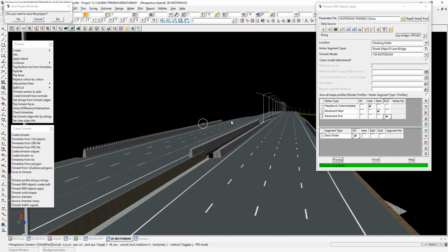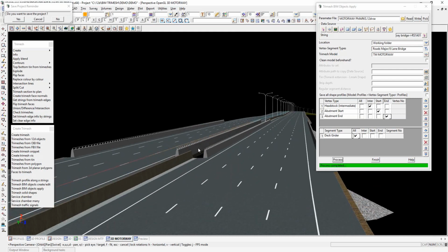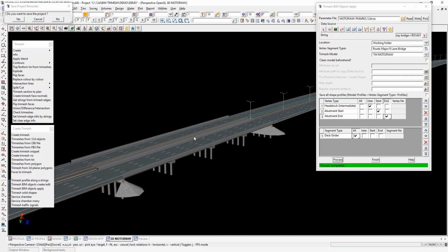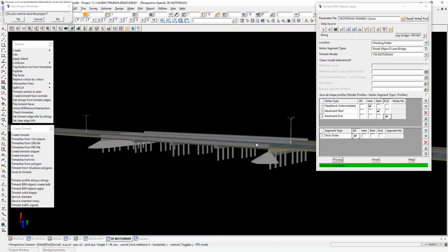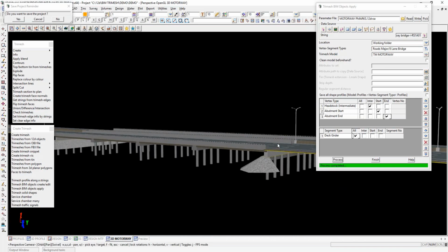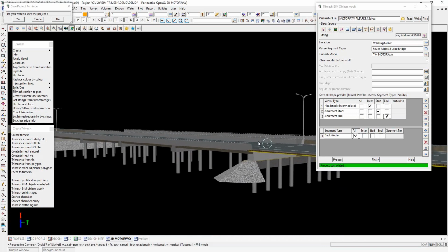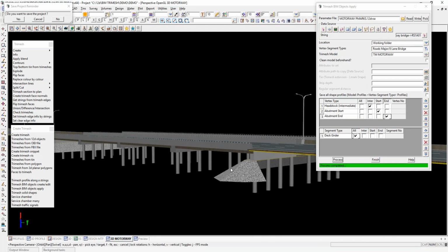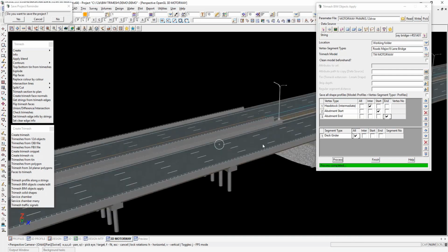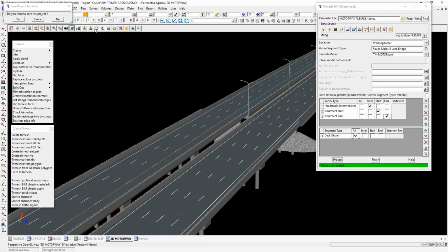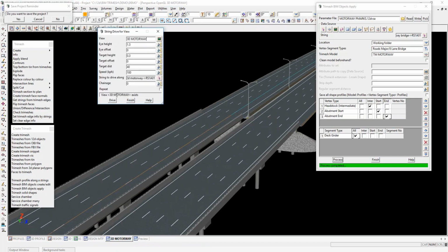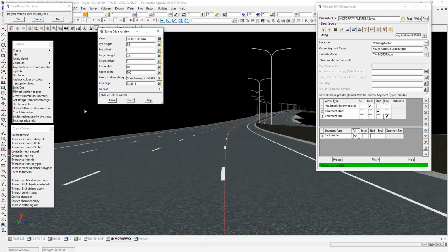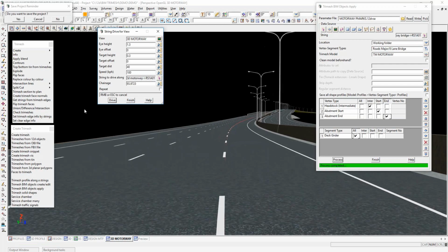As I said, it's a concept idea. It hasn't done all the details for what happens on a normal road design, but it also did it in 3 minutes. So the idea is you can utilize this. If you do specify a tin surface when you do the bridge, it will actually trim off these pylons and also this spillway into the actual tin surface itself.